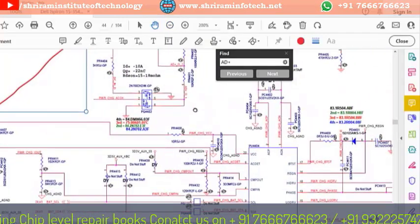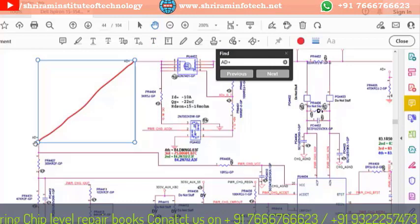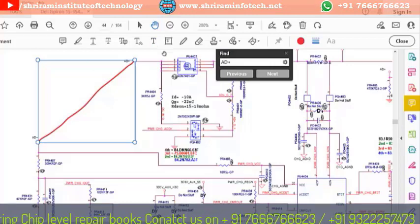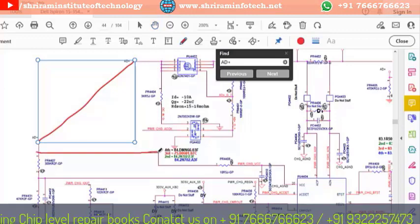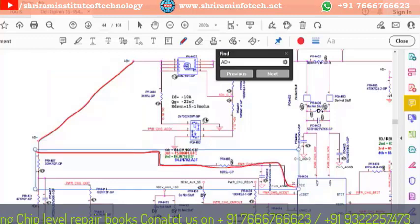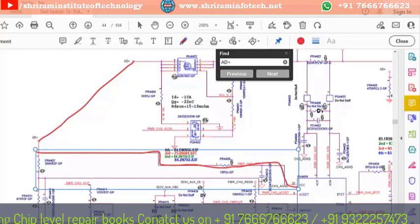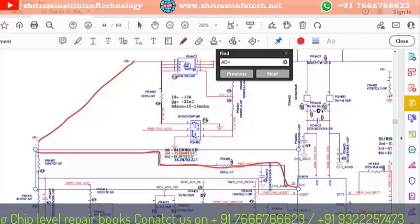The PU4404 will get how much voltage? See, the DC plus and DC plus are both connected to each other, that is a single track. Now this 19 volt, the same voltage will travel from here to here to here, to the DC in pin at pin number 20. So you should get 19 volts at pin number 20.